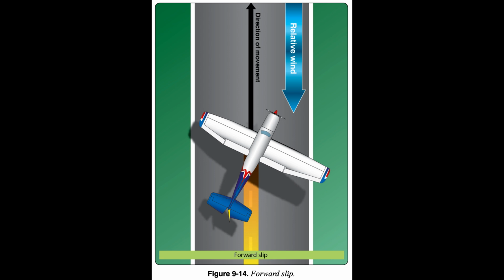Note that some airplanes have limitations regarding slips. In some cases, slips are limited in duration or by fuel quantity. These limitations are meant to preclude fuel starvation caused when fuel is forced to one side of a tank in uncoordinated flight. If a forward slip is being used to reach a landing area in an actual engine-out emergency, the time limitation or fuel limitation is irrelevant, unless a prolonged slip caused the engine issue.